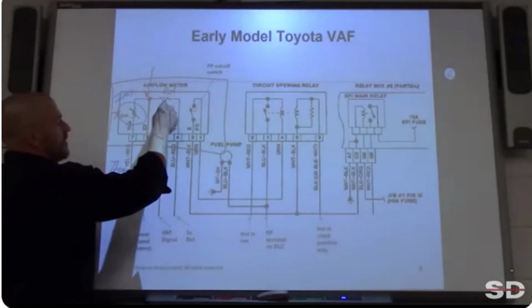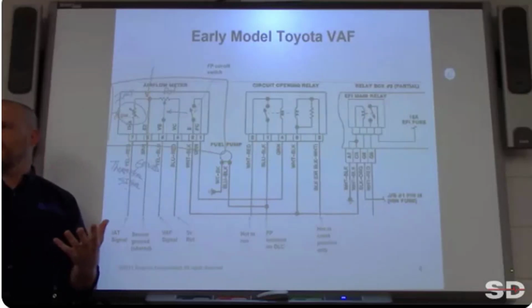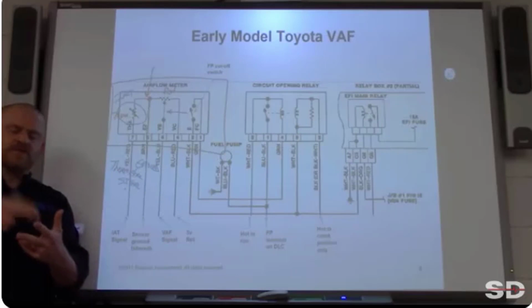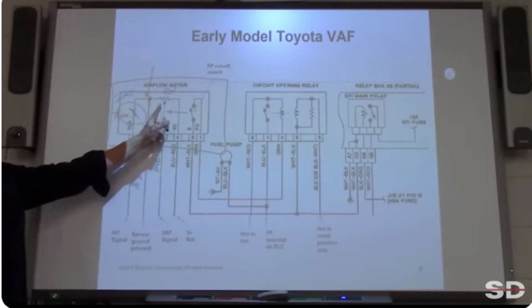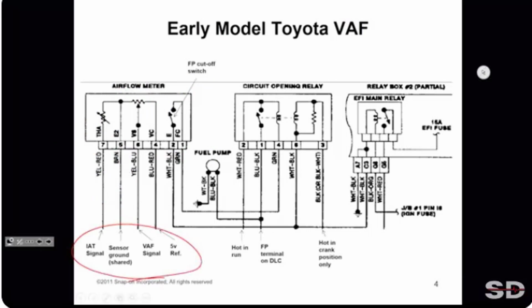And then another clue for you guys would be the pointer on a potentiometer would be your signal wire. So we have 2 wires left, right, on the pot. We have the ground identified already, so we just have a signal and a reference. The signal would be the pointer. And so what's that make this circuit? This is my 5-volt ref. And you can see down below that I have this all identified for you. I have it written down right there. Just a little sensor review.